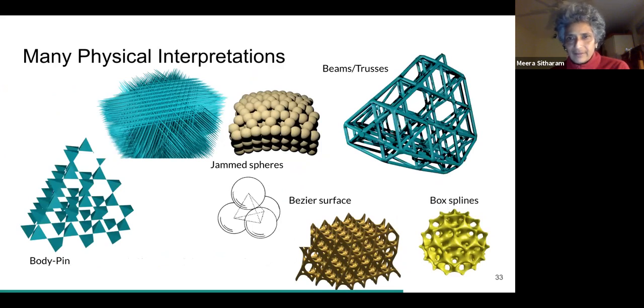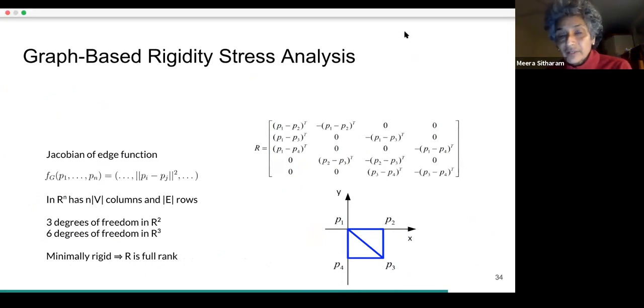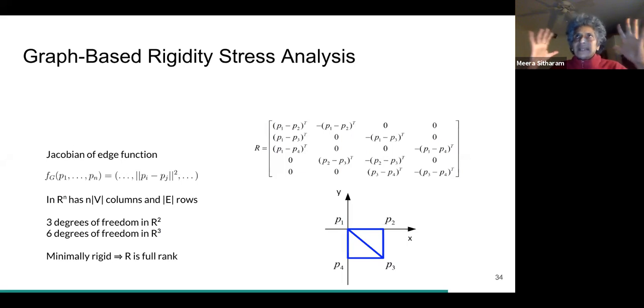So finally, as I said, we can use a discrete analysis of the various properties, mechanical, electrostatic, whatever, and do it really quickly by just using the discrete representation directly. We did some of that, both directly using the discrete representation for computing stresses and connecting that with the representative volume element, to use the discrete method to figure out what the representative volume should be. Representative volume is the minimum volume of the irregular microstructure that can then be treated as homogeneous, right?